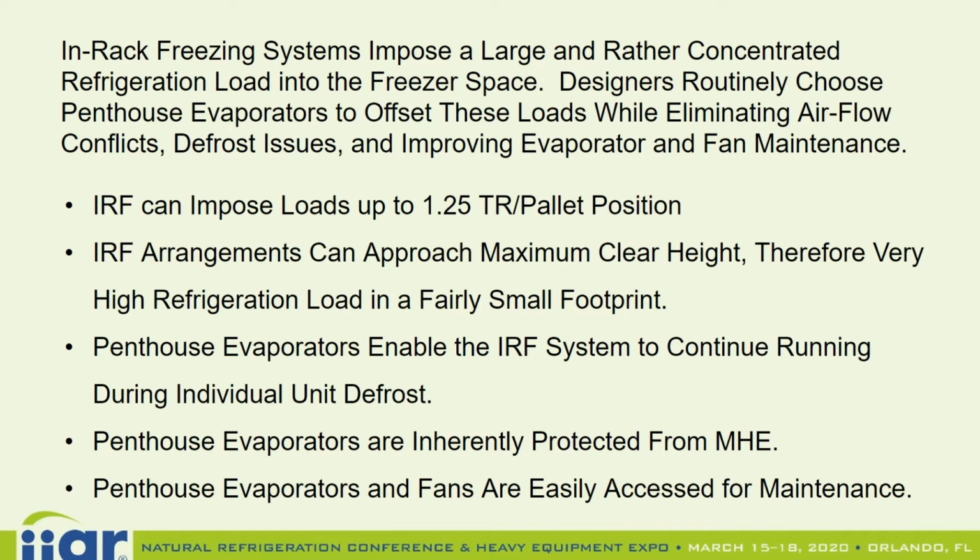The next advantage is the ability to continue to run the in-rack freezing system while individual penthouse evaporators are defrosting. You may have 6 penthouse evaporators in a freezing area, and you don't have to interrupt the freezing process happening in the in-rack freezing system to adequately defrost one of the penthouse evaporators.